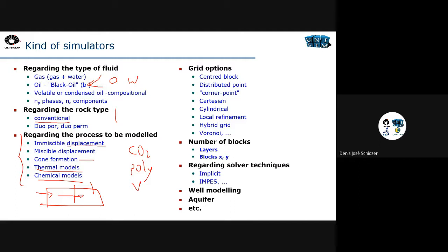But on the other hand, if you're going to inject CO2, if we have a light oil, if the pressure will change a lot, if you have a model with fractures and vugs and karsts and so on, then we're going to have to use a very complex simulation model. What's the difference between these? We're going to show in the equations today and next class, probably in the third class from now, trying to explain the difference in the model when we have these different aspects, okay?